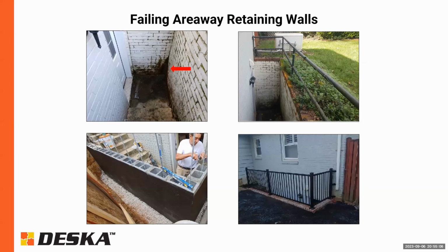This wall in particular was a double width brick wall. So there's really not a way, you can't put shear pins inside of it. You can't use carbon fiber straps because there's nothing to attach the top anchor to. And if you wanted to use steel struts, they're going to sit in too far and you're not going to have enough clearance in your staircase any longer, and it would become a code issue.